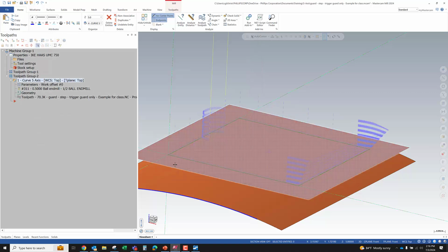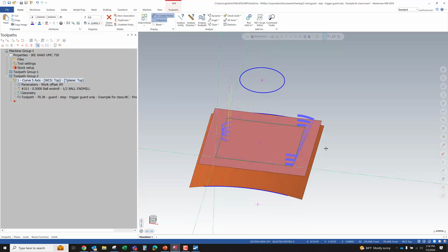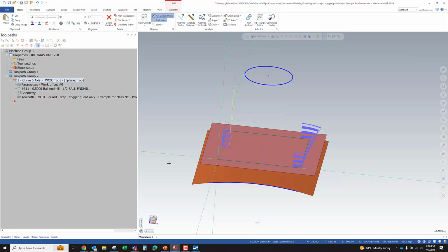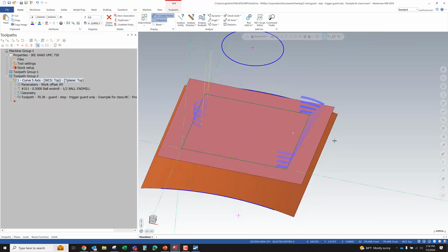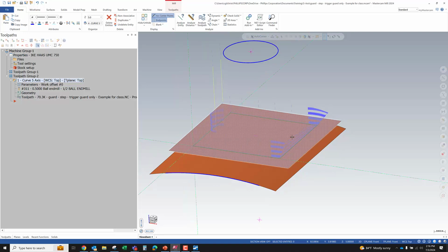The other situation that we'll run into is where we need a check surface. And in general, a compensation surface in Mastercam is something you want to cut. A check surface is something you want to avoid. But in 5-axis, it's often sometimes better to just add an additional compensation surface and offset it, because if you just put in some kind of avoidance surface, now Mastercam has to decide what to do. How is it going to change the toolpath to give you what you want?